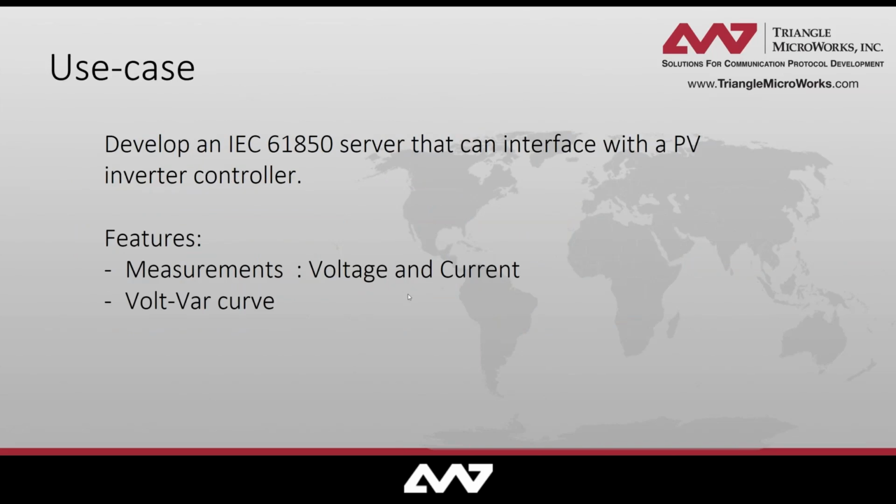The use case that we will be looking at today is an IEC 61850 server, and we will show how you can get voltage and current measurements, and then a simple example where you can send out multiple volt-var curves, where you can update it, and how the total var changes based on your curves.